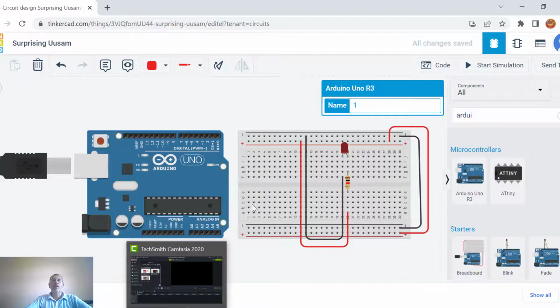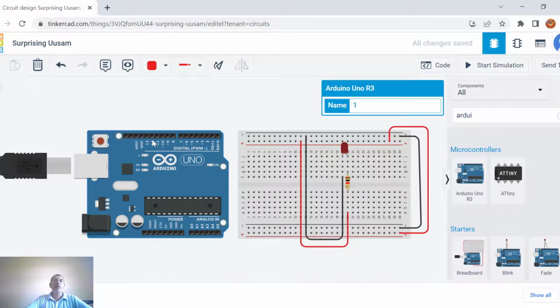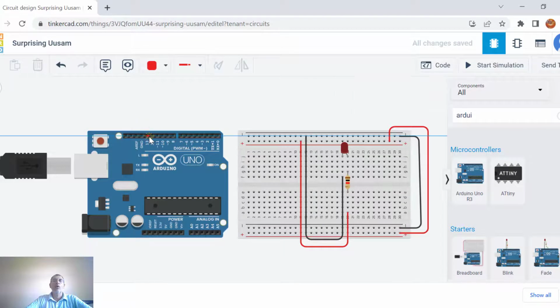So now let's do this. Let's connect a pin, without getting into details in this class why we're connecting pin 13. So we're just gonna go pin 13, and we're gonna go to here. Okay, and then we're gonna go to ground. You see where the ground is? And then we're gonna go like that. And as I said, a good habit is keeping everything color coded.